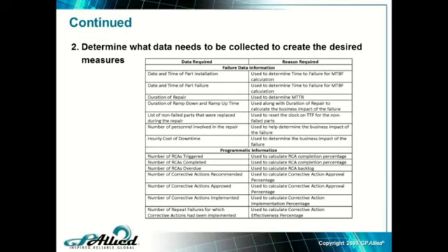I'm a little bit different about measuring. A good metric would be rework. Rework to me should be measured. If I have a failure on that asset within 90 days, then that's rework. Some people say, well, SMRP says 30 days. Okay, that's fine. I say 90 days because the problem is, unless we perform root cause analysis and identify exactly what the root cause of that failure is, it may occur again and we call it something different. I just want to know if it happens in 90 days. That's all. I've done this for a lot of organizations, and I'll tell you what, it brings a lot of value.